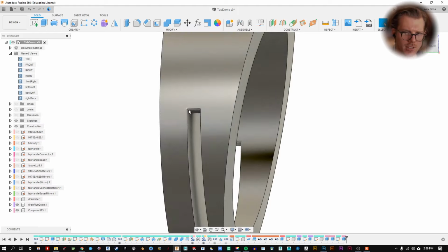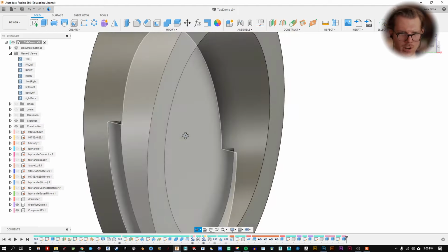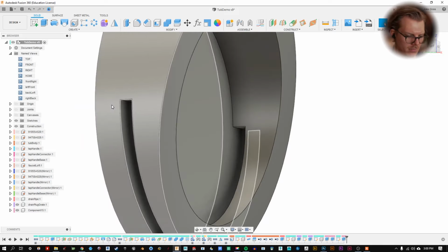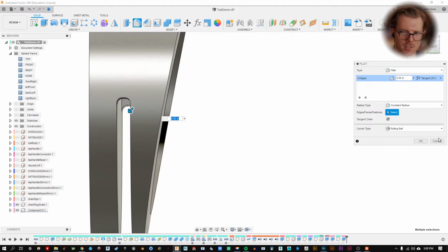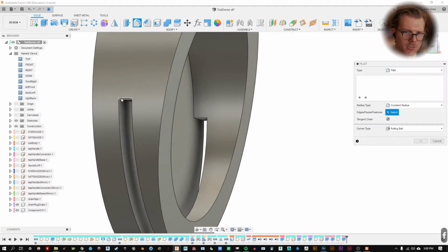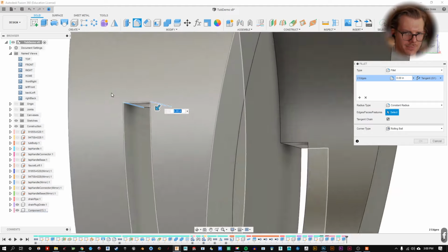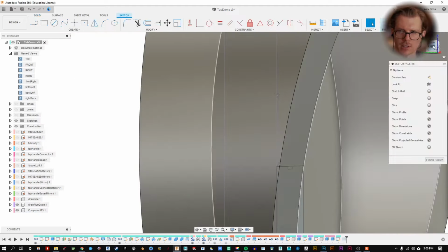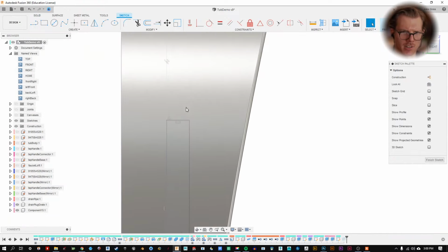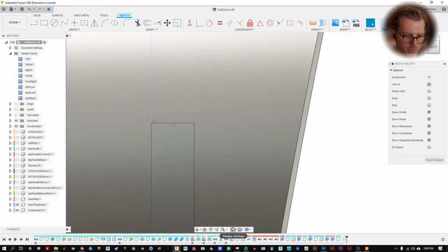Now in actuality, cutting this way might not be visually great, or I don't know, let's call it visual. Actually, it could be cut pretty easily, but let's go ahead and fillet this and just make that look a little better. We could have done that in the sketch, or we could do it in a feature. I'm hitting F on the keyboard, taking those intersections. Another way I like to do things in the sketch, I'm jumping around now, I know. Go back to wireframe.